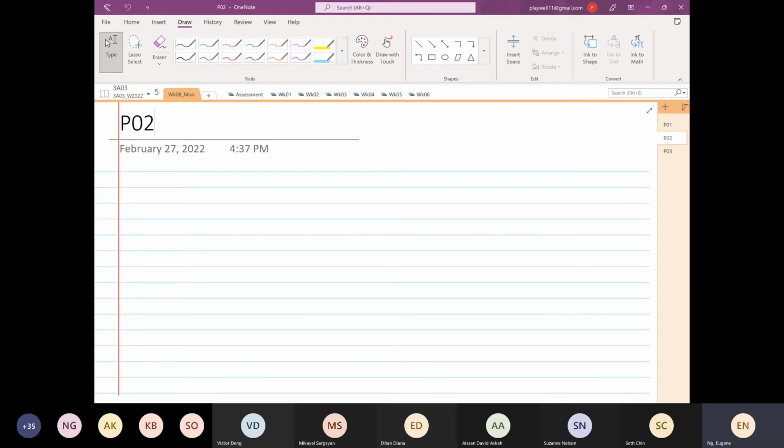So we have learned two big formulas. We have learned that stress in X is equal to Px over A plus My over Iyy times Z plus Mz over Izz times Y. I told you guys not to worry about the sign, as I teach you how to visualize the sign.